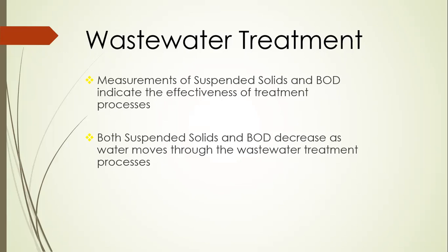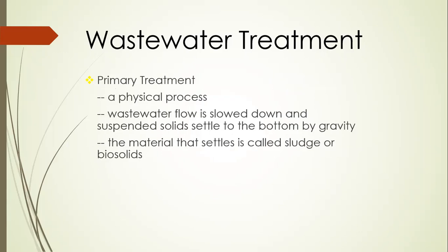So at different processes, you will measure the wastewater characteristics with respect to suspended solids and BOD to monitor the wastewater treatment efficiency. So typically, both SS, that is suspended solids, and BOD should be reduced as we move on through the wastewater treatment process, as we can understand.